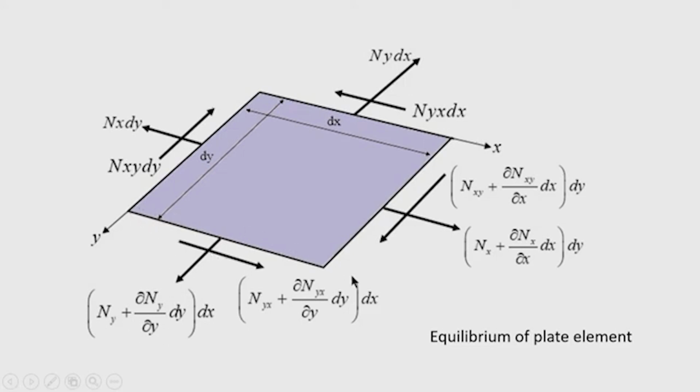Okay. Now, there are in-plane shear forces that give rise to a compressive force along one diagonal, and along the other diagonal there is a tensile force. So, you can see here, if you take the resultant of these two in-plane shear forces, that are acting along the edges, tangential to the edges, then you will get the resultant as the tensile force along the diagonal.